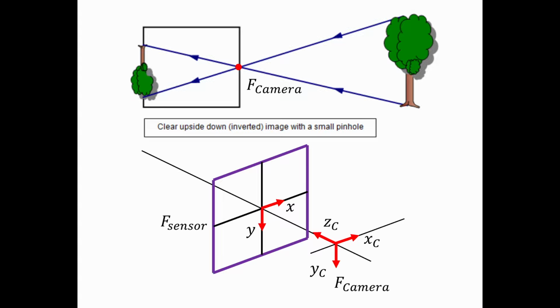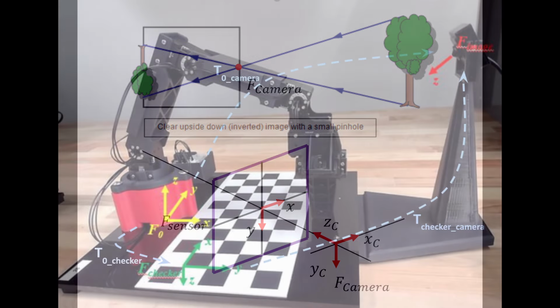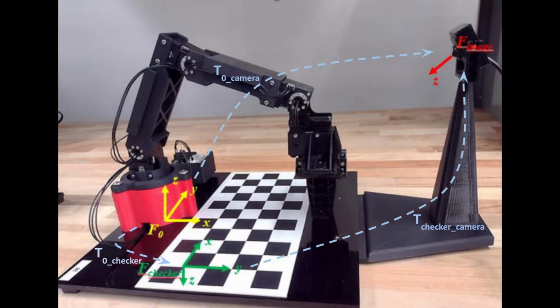To be able to actually implement any of the previously mentioned strategies, we need to introduce a camera that we can use to analyze the color and location of the balls in our workspace. We use a simple USB webcam. With MATLAB's Camera Calibrator app, we are able to remove the camera's fisheye lens distortion and translate the location of the pixels in the image to the coordinates on the physical checkerboard using the intrinsic and extrinsic camera parameters. These parameters are calculated each time the camera is calibrated to the checkerboard.